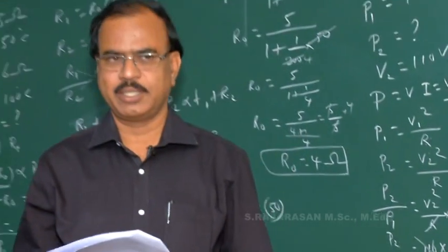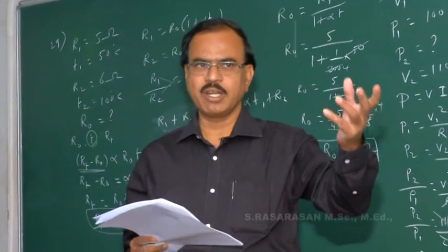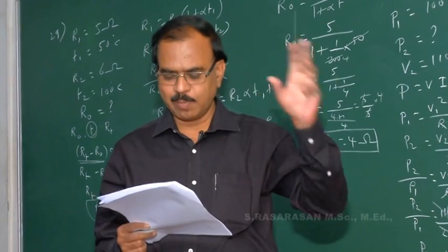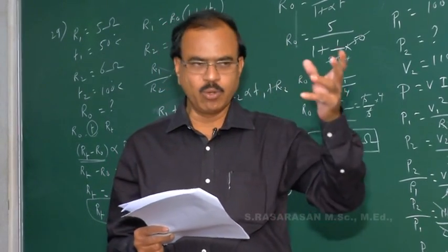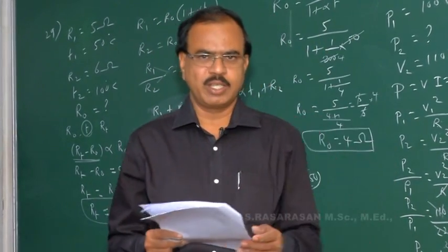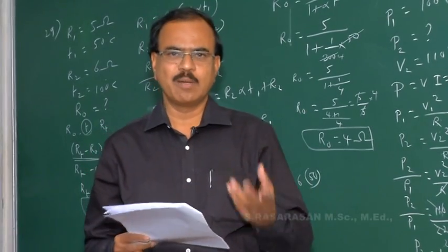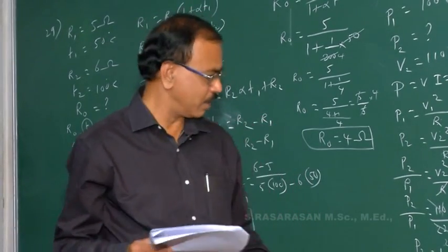Actually the bulb is rated by 220 volt and 100 watt. If there is 220 volt potential, the EMF gives 100 watt power. When 220 volt goes down to 110 volt, the potential drops, and the power comes to 25 watt. That is a proof.